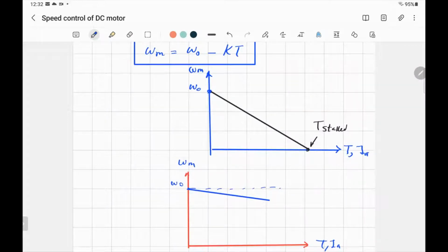It increases. So they apply a small amount of voltage to the terminals of the DC motor to be sure that the armature current will not exceed its limit. Why do you do that? For testing the DC motor, you can use this value to measure the constants of the machine, such as the armature resistance. Maybe somebody will say it's easy to measure the resistance of the armature by putting a voltmeter just across. No. In the DC motor, every time it rotates the angle changes, and the resistance changes.